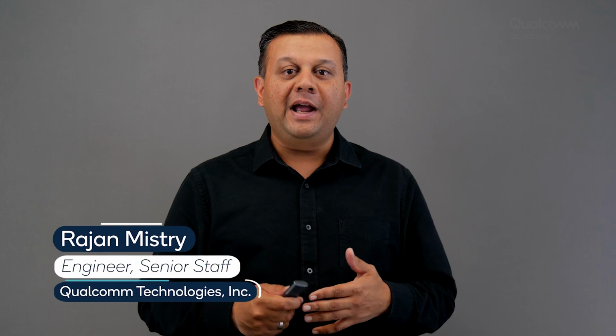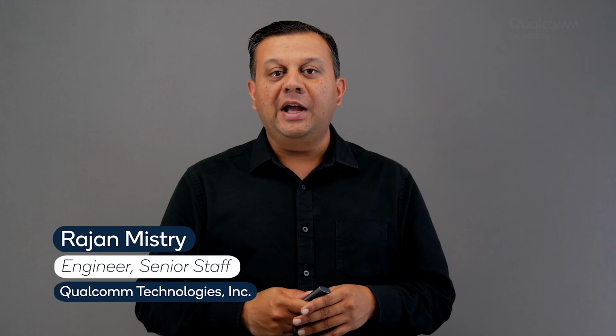So to recap, in this video, we gave you a brief introduction on ROS. We showed you how to install ROS on the Qualcomm Robotics RB5 development kit and how you can use ROS to collect some sensor data using ROS nodes. We also had Ramya walk you through the TurtleBot 3 setup, how you can install TurtleBot 3 packages on the dev kit, and how you can use the dev kit and ROS to control the robot. We also had Rahul walk you through similar steps on the MBot dev kit and how you can use the RB5 development kit to control the MBot robot.